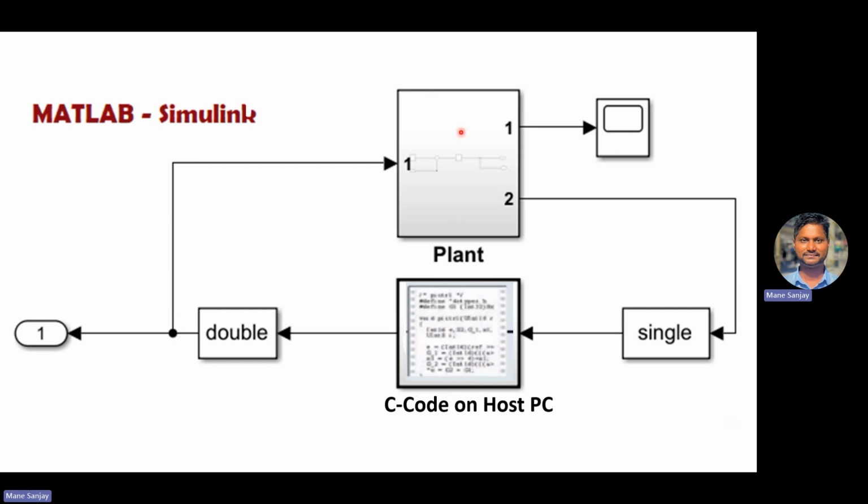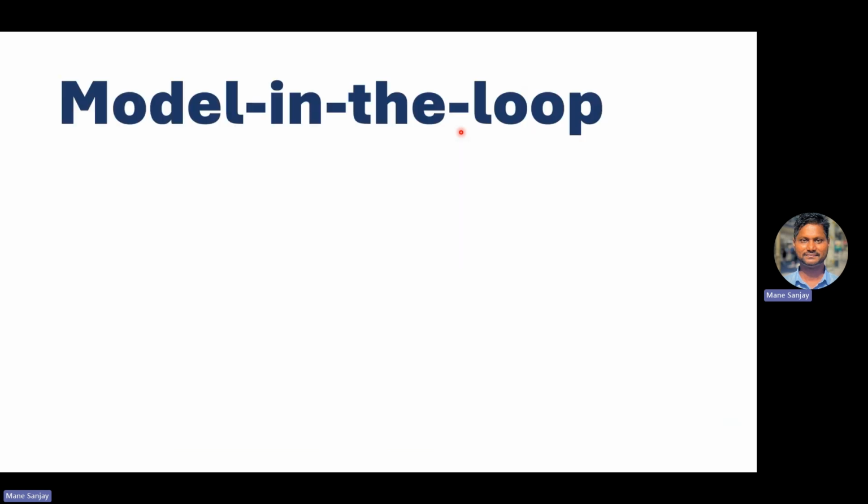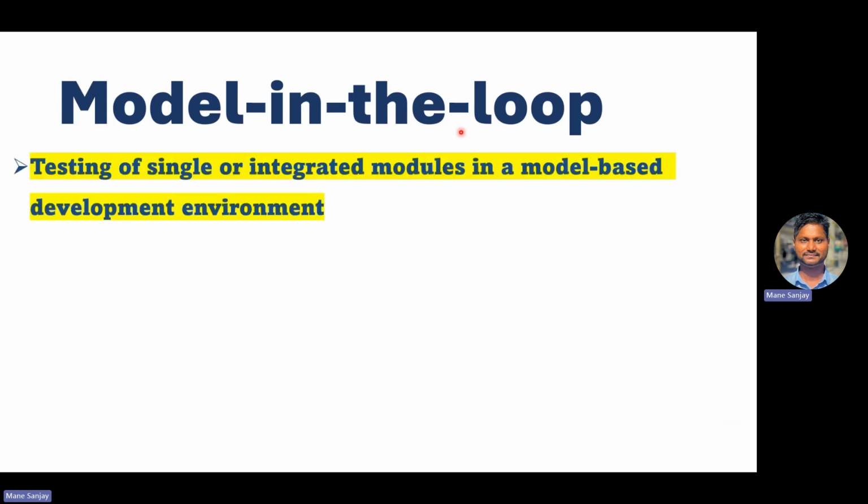This entire model runs on the host PC. No need to use multiple PCs or multiple software. That is the beauty of this SIL. So let's jump to the next topic, that is the model in the loop simulation or the model in the loop testing. This testing is also called MIL testing or the model testing.